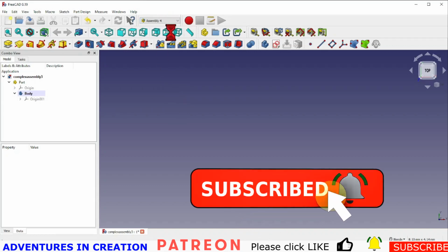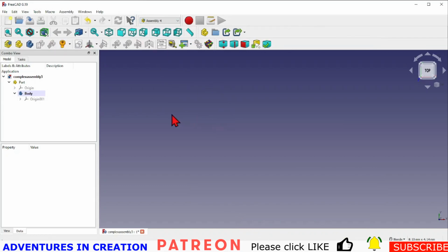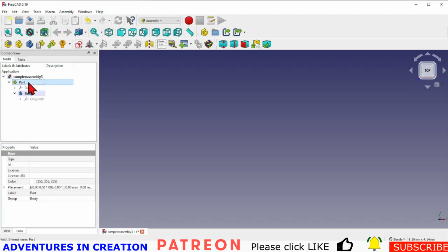If you don't have the assembly 4 workbench showing up, you may have to install it. You just add the workbench. We've done that in a previous video, so you should be able to go back and take a look at it. Now I'm going to make sure that my part is current. So I just double clicked it to make sure that it is current, and then I'm going to select create new assembly model.